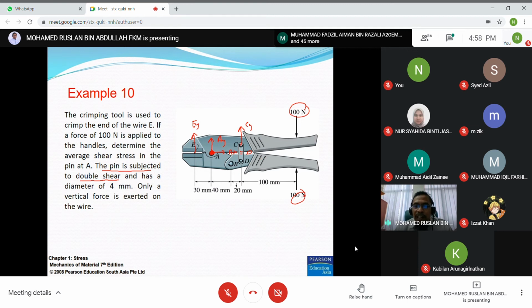When AX equals 0, we have 3 unknowns: AY, EY, and CY. So how many equations do you have? You need at least 3 equations. Based on the equilibrium, here how many equations do you have, 3 or 2?